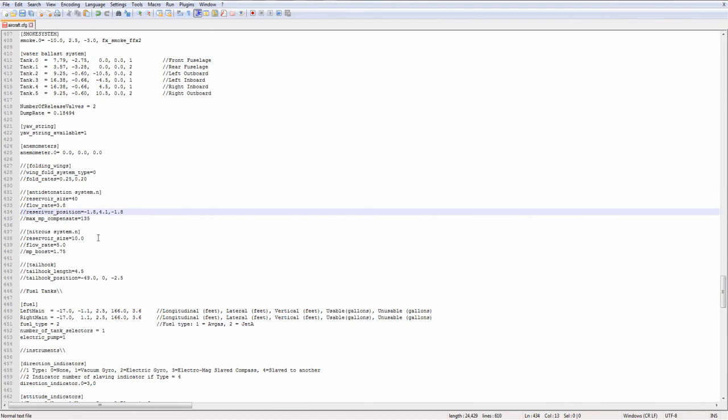Anti-detonation system. Now, we talked about the detonation thing with the engines. For piston engines, this is the anti-detonation system. And all this is basically a fancy system that will squirt water into the cylinders to keep detonation from occurring. Refer back to our engine section to talk about what detonation is, but when this system's turned on, it doesn't turn on automatically. It has to be triggered by the pilot, but when it's turned on, the detonation will be delayed. It won't stop it entirely, though. You'll find out why here.